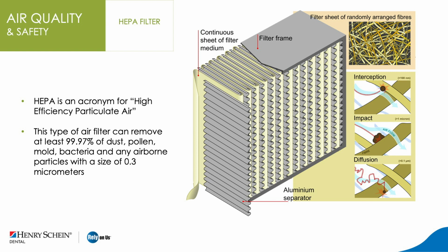So I'm not going to recommend that we're using negative pressure throughout the clinical zone, because you'd be spending hundreds of thousands of dollars on an HVAC system. And honestly, I don't know that it's that effective. But this is what we will recommend. Consider using HEPA filtration in at least the clinical zone, and have separate heating and air conditioning zones for every architectural zone.